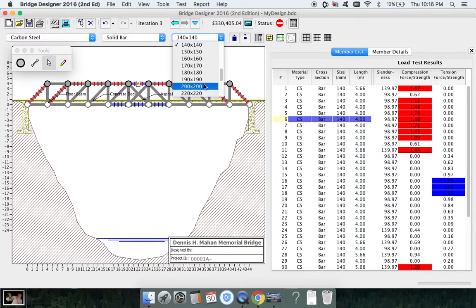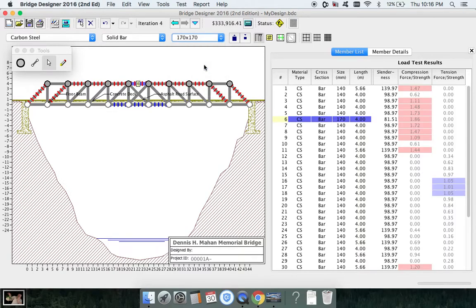You can increase the thickness of that piece, which increases your cost. You can make it a hollow tube instead of a solid bar. Solid bars weigh a lot, and if your bridge is solid, it has to support itself in addition to the truck. You can change the material to a stronger material. So that's what I'm going to do. It does add a little cost, but we'll give it another try.